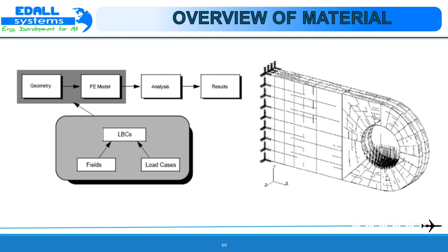In Patran, different individual sets of loads and boundary conditions are grouped into quantities known as load cases, which essentially constitute a separate analysis solution using the same model data. We will discuss load case capabilities in Patran later in this session.